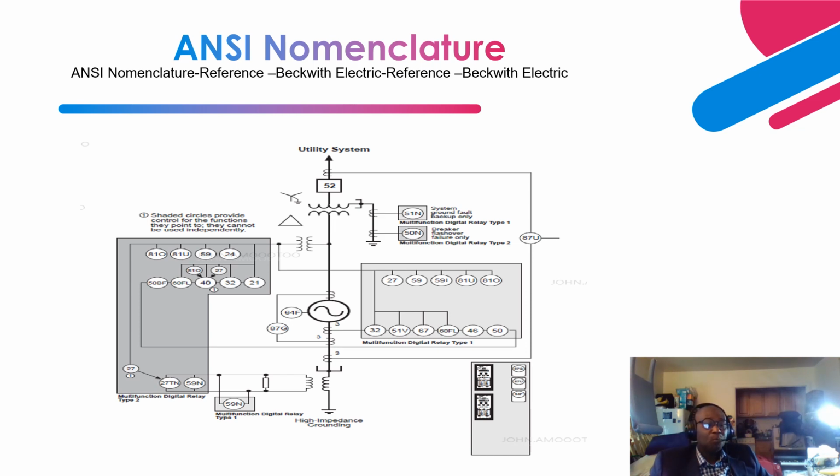Next is ANSI device 21, and this is a distance protection. This relay acts as a backup to the main differential protection, and what it's looking at is the generator's contribution to a fault in the AC system.